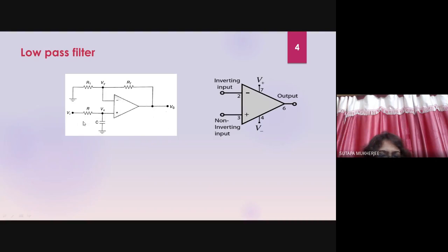Now AF equals 2, fc equals 2 kilohertz. Then if you want to design the filter, you have to know R1, RF; these you have to find out. How can you get it? Well, definitely this C is also unknown, right? Yes, ma'am. So assume that C equals 0.01 microfarad. So what is known? fc is 2 kilohertz, C equals 0.01 microfarad, and then calculate R.